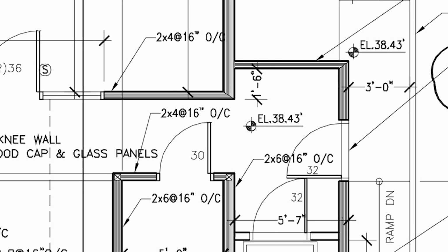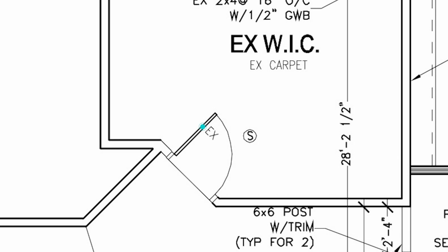A lot of my customers in the past didn't necessarily understand how doors swing. So let's look at the door symbol and see what it reflects. This represents the door, and that means on this side the door hinges, and on that side will be the door knob. And this shows the door swing. And this line represents the area that you should not cover with any furniture, because the door needs to swing back and forth.